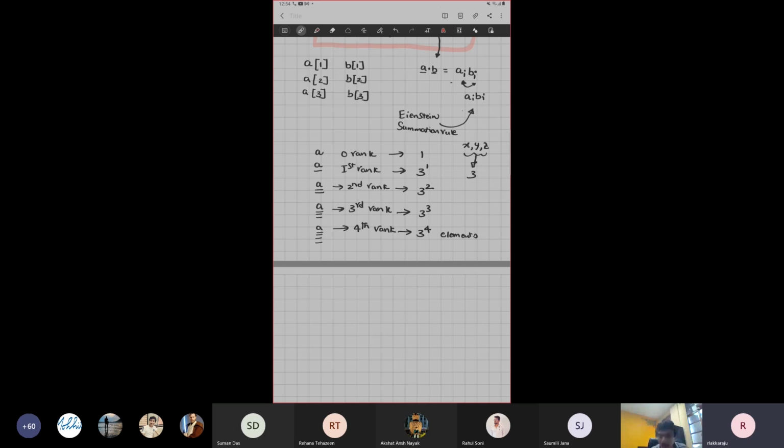In Fourier's law of heat conduction, heat flux is equal to K multiplied by A multiplied by del T by del X. The del T by del X in 3 dimensions becomes del T by del X, del T by del Y, del T by del Z. That means heat flux is not a scalar, it becomes a vector.